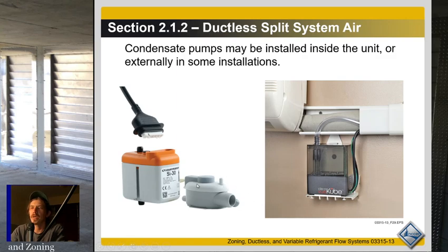Some guys think that the pump is sitting inside the unit, but usually it's not. Usually these little mini split pumps, this is just a reservoir with a float switch. When the reservoir gets full, this pump comes on. And this pump can usually be so many inches, I think up to like 18 inches or something like that, above the reservoir.